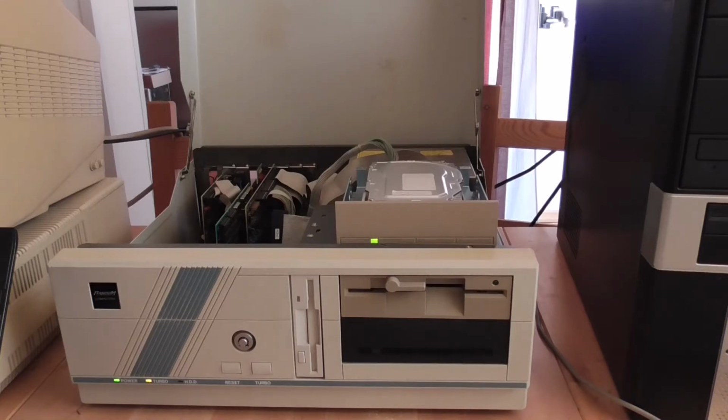It's a 615 cylinder drive with 4 heads and 26 sectors per track. It has 38 megabytes unformatted and 33 formatted. So I'm kind of hopeful that it's going to work. I don't know for sure that it's compatible with my controller. It's an ST412 interface, and it's an RLL drive, which I've not used before, so this is run length limited, which just sets the maximum number of bits that can be all the same. I'm not really too familiar about all the details. I'm just reading from the Wikipedia article there, but it does seem to be formatting okay using the low-level format utility, so I am hopeful that it is in working order at this point.